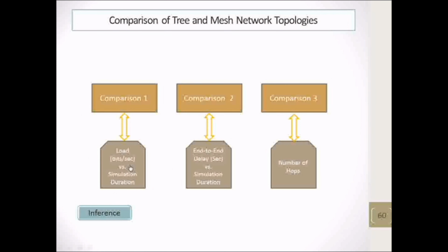This is the hardware. This is the step down transformer for powering up the ICs, and this is the power supply circuitry. It comprises a full wave rectifier and voltage regulator, and this is the MAX232 circuitry with its biasing capacitors. Now we will see the final hardware results associated with the serial communication hardware of the monitoring area module.